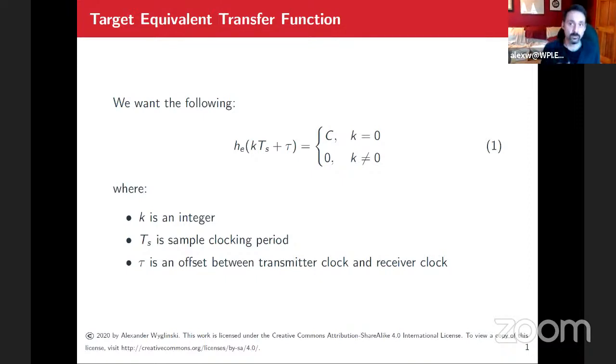That happens a lot. If you take my software-defined radio class, I'll be talking a lot about the timing offset between two radios, because they both have their own crystal oscillators, therefore their own clocks, and you have to account for that time difference between the two. So the tau is really important for aligning the transmitter and the receiver in terms of the symbols that come across, so you sample at the right point at the receiver what has been transmitted. So what does this mean?